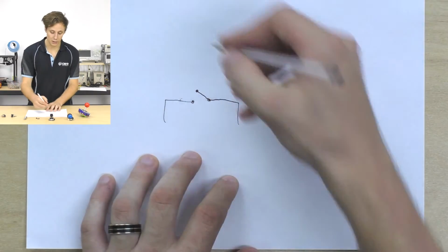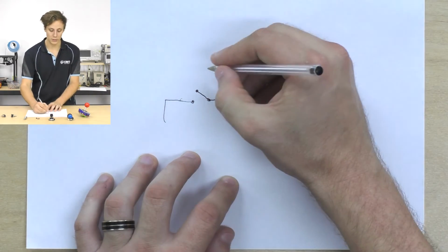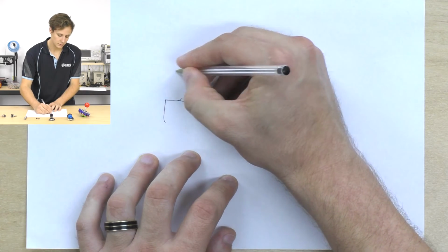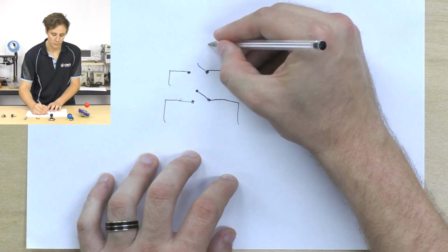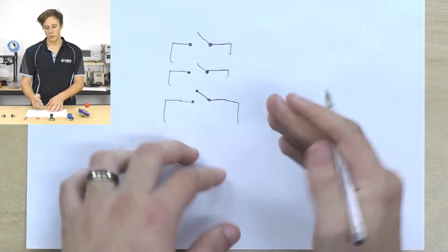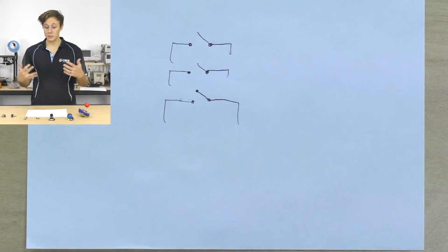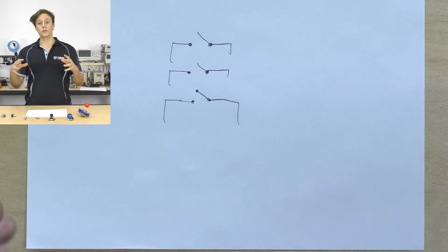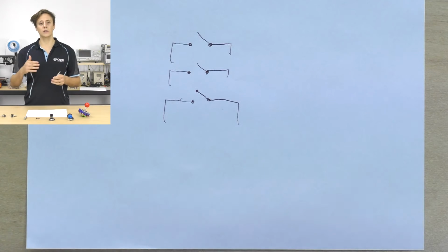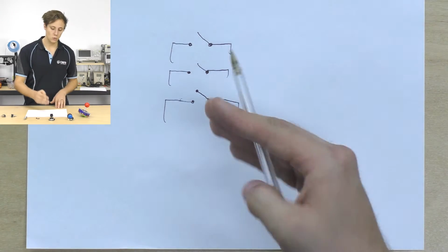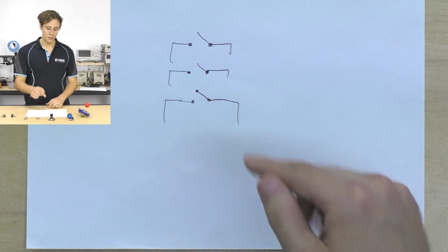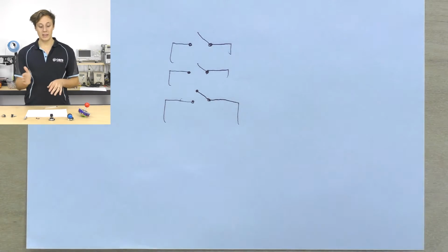In a schematic, you could imagine that inside one mechanical switch, we have another 2 poles which can be switched and manage their own signals independently. Throws are something different altogether. Throws is the number of contacts that a single pole can make, so the number of options, if you will, that that one pole can be connected to.